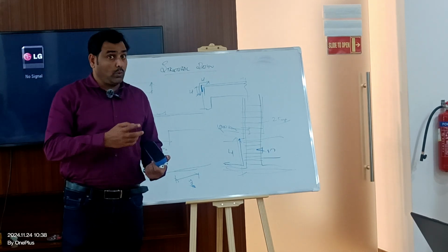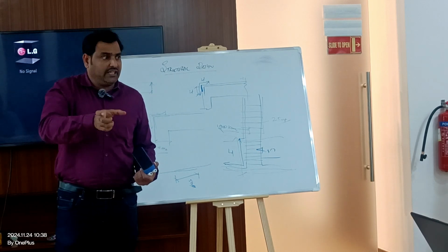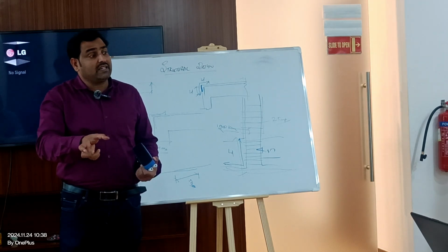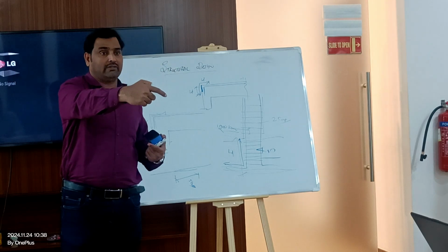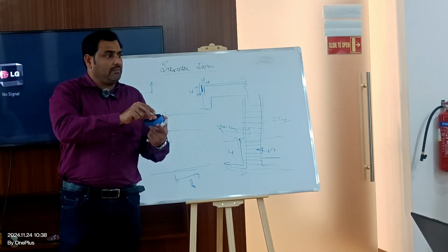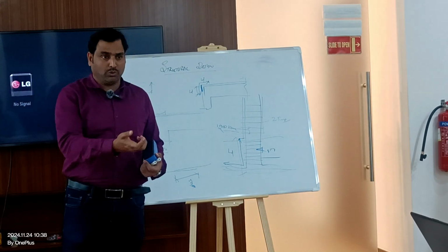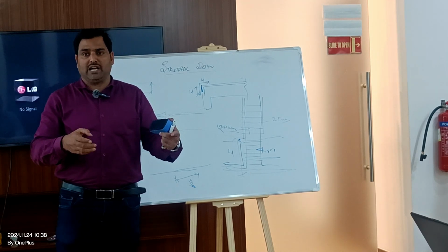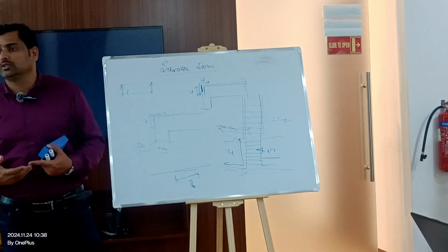The one you are talking about, if you miss the rebar for the continuous slab, then I need to calculate precisely the load, because while going for post-fixing using chemical, I cannot go for a longer development length, as you say 50 times. That's the reason you will see 150 millimeters, 200 millimeters, whereas in reality it will be 600, 800. Sometimes with post-fixing it is only required for 300, 250.